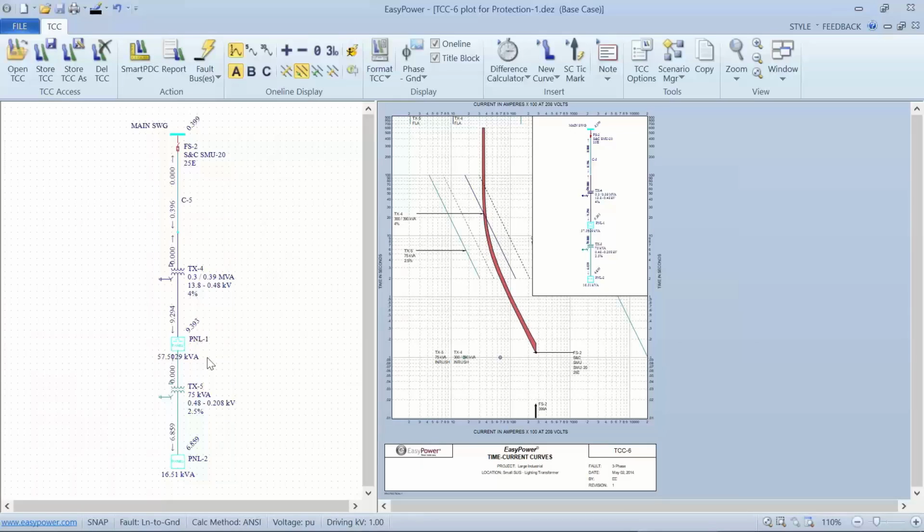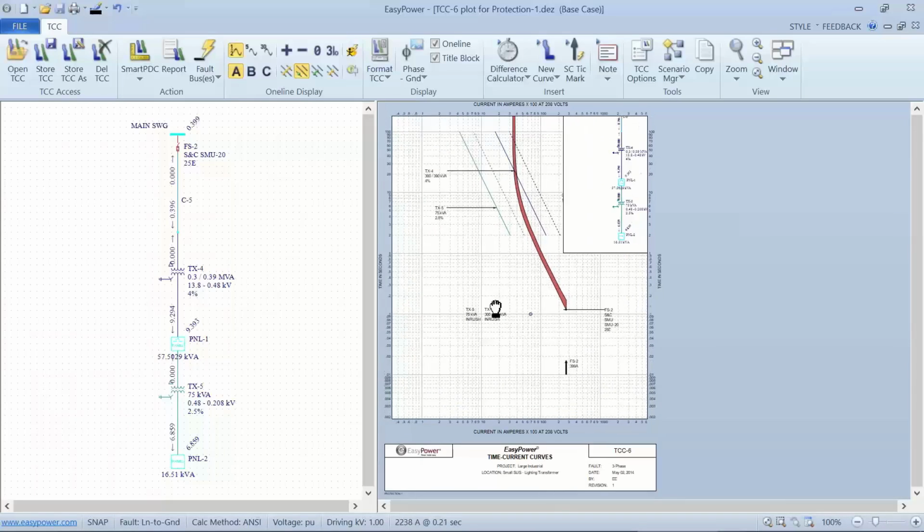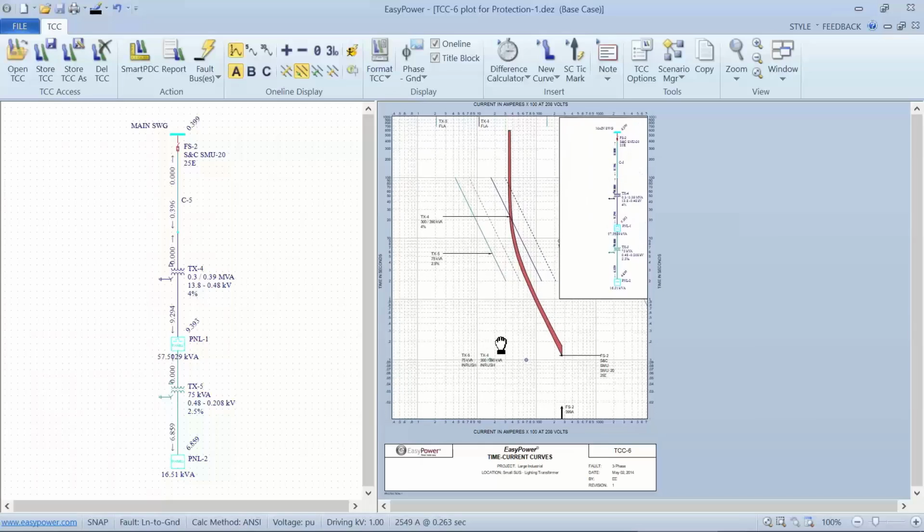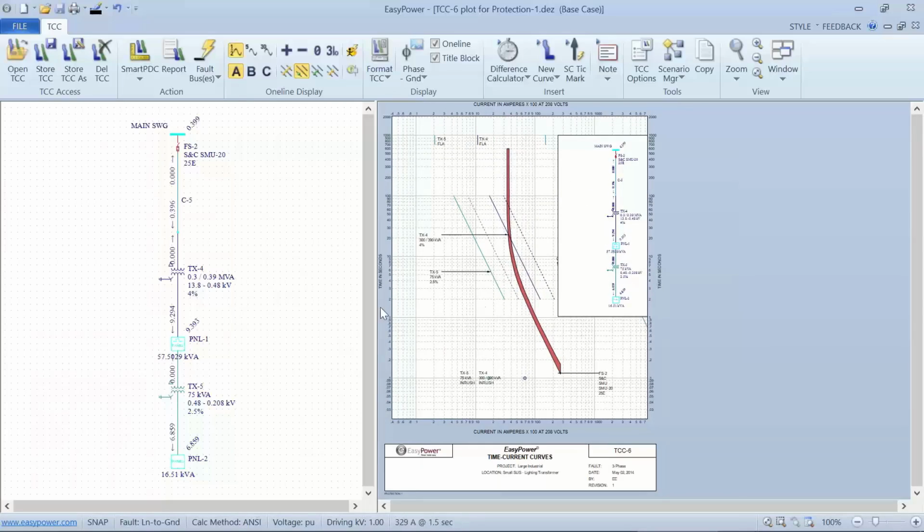In fact, I think on this one, yeah, this one has problems too. So this would be worth walking through. For instance, the fuse is the only thing it's showing, and it's possible to have coordination with the feeder breakers and main breakers in a panel. Oh, sorry for kind of stomping all over that.